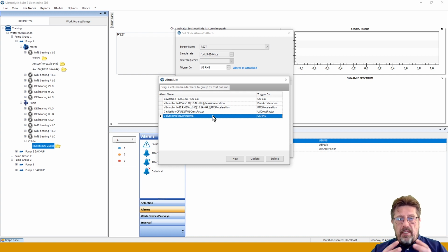I'm trying to explain this to you in this way because at the beginning of your condition monitoring program and using UAS3, you don't have enough consistent data, and you are not yet working with the assets enough to have them all stabilized to a certain level with more or less consistent data, and you cannot understand the asset based on one measurement. So at the beginning you will probably start with node alarms individually.